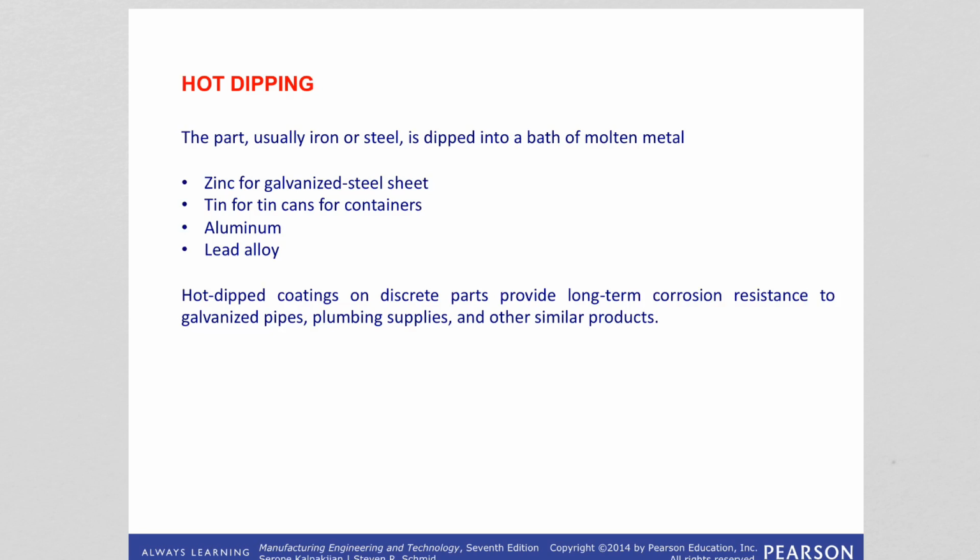Remember, if you learned about corrosion in your educational life, zinc here acts as a sacrificial anode to the iron, and it dissolves, it corrodes itself, protecting the iron. So this is an example of the hot dip galvanizing process.